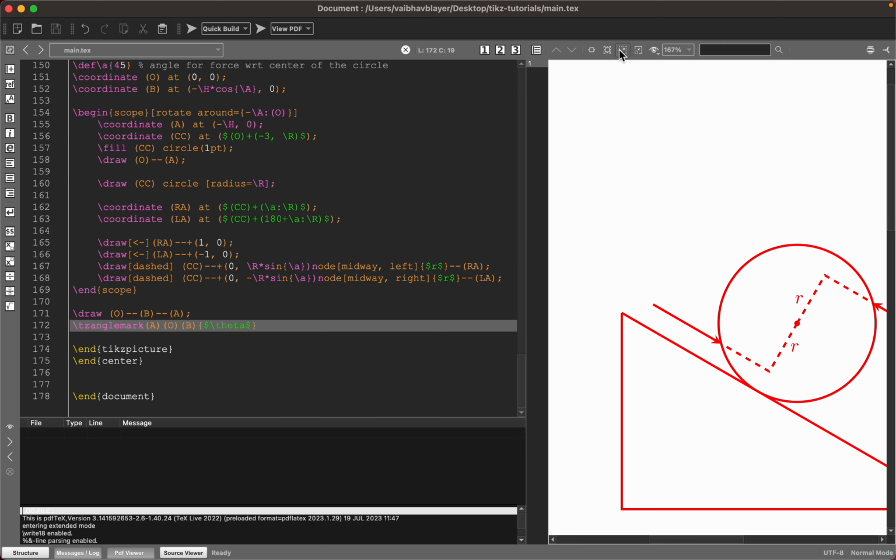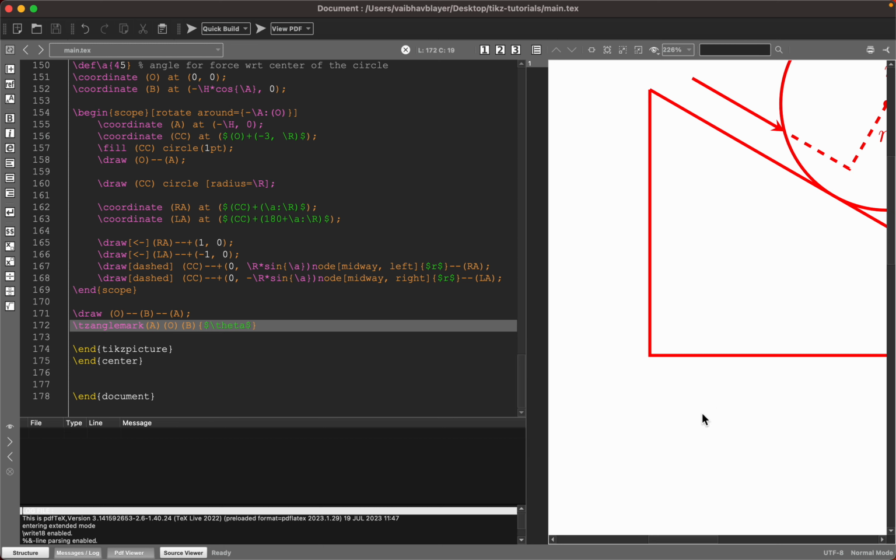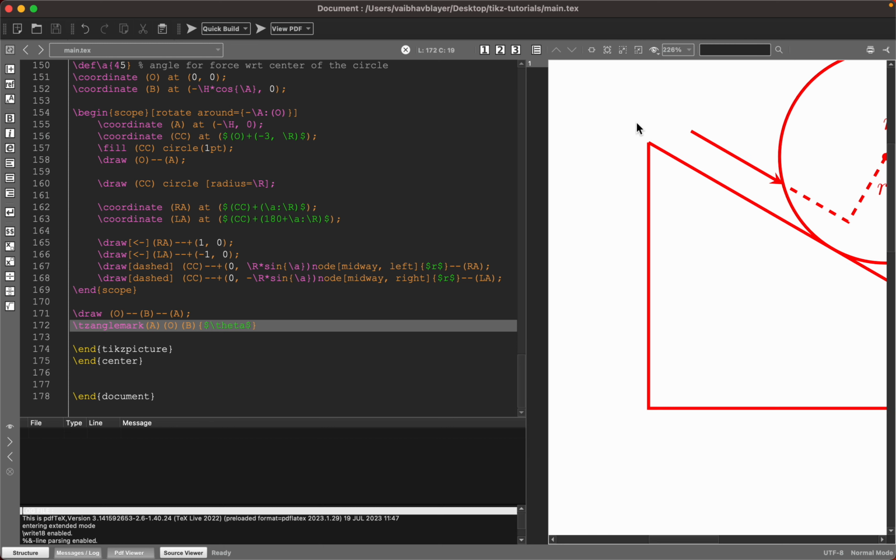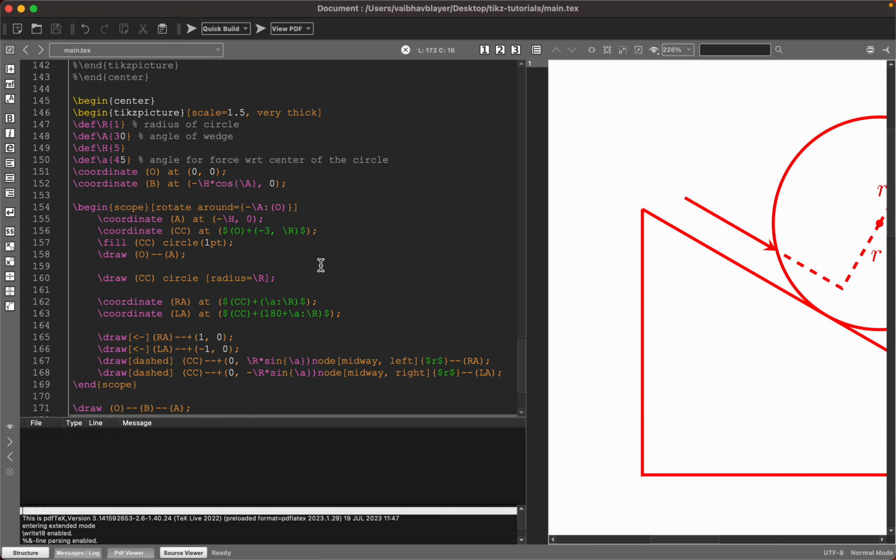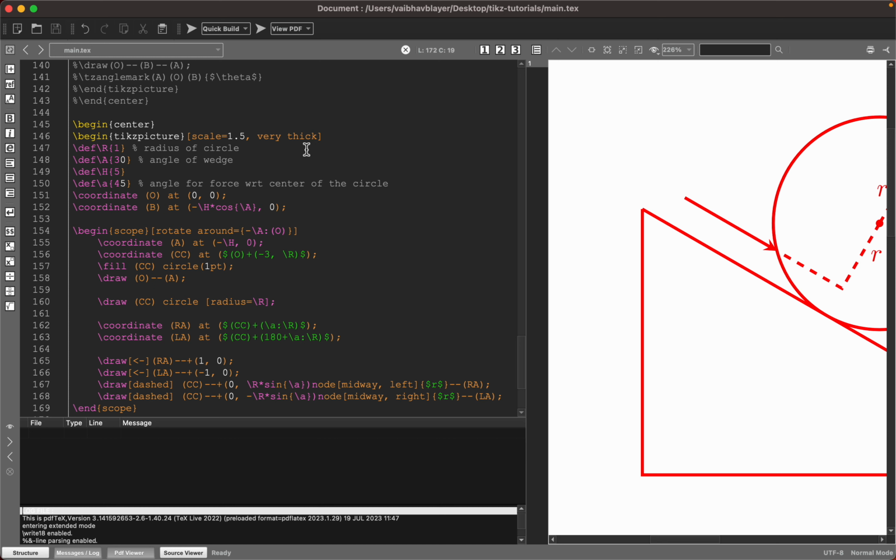As you can see, when we join the lines, they just do not join perfectly. It's like an error, and the arrow also does not look perfect. So for that, for the whole thing, we are gonna use the cap of the line equals round. And one more thing, I'm gonna use the arrow as latex arrow, like this.